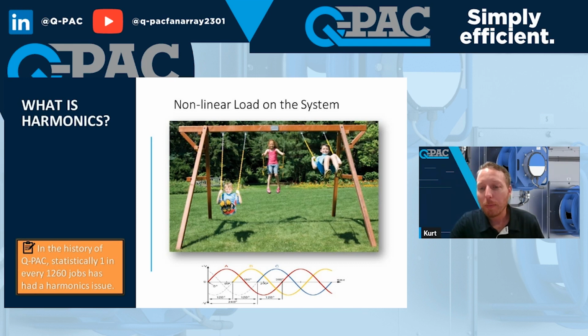And another thing to mention, the harmonics. A lot of people reference IEEE 519 for harmonics. That is a standard at the point of common coupling and not a component standard, which means that whenever you're checking for harmonics, you need to check for it at the transformer that's feeding many, many devices in the building, and not just a component.